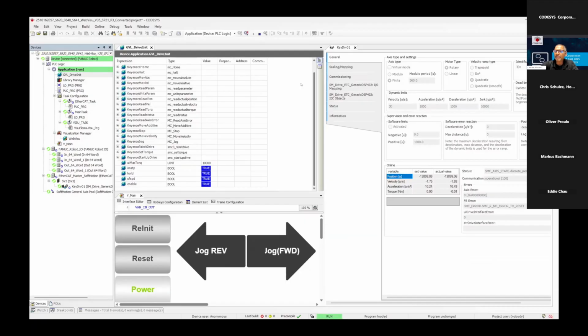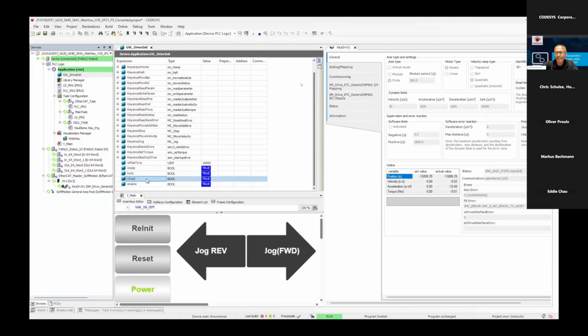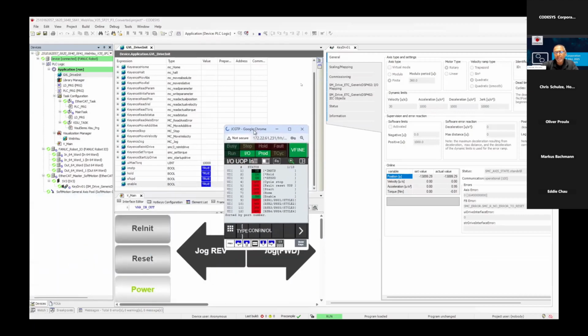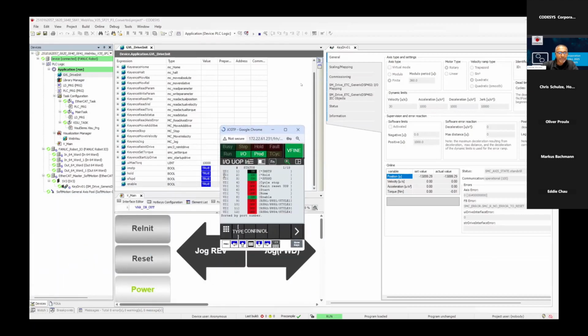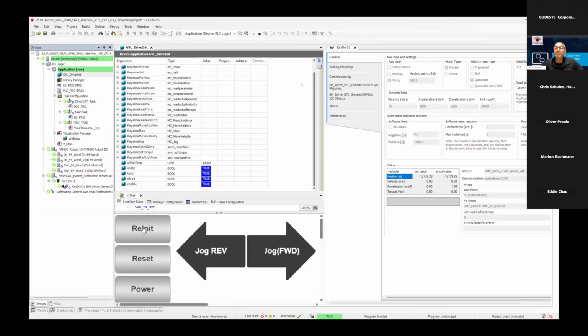And at the same time, we can access the robot controller's web visualization via a web browser, and both have control over the motor. I'm also highlighting the I/O that I've turned on in CODESYS so that the controller is in auto mode. Those signals are the immediate stop, the hold signal, the safe speed, and the enable. Again, if time permits, rather than looking at this video, I'm going to attempt to show a live demonstration of this as I have all this material configured in the lab, and I will be accessing it remotely.